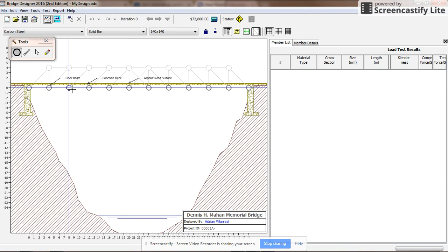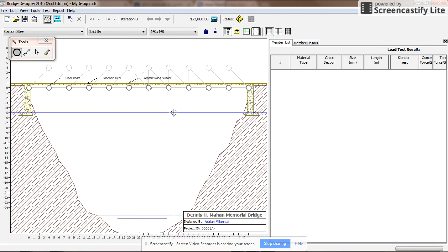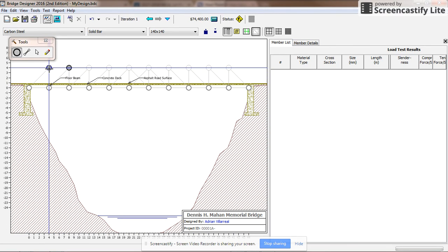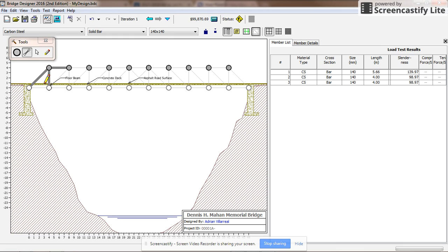So now you get this, guys, and you'll see there's an outline of what your bridge should look like. Wherever you're going to have beams connected, you can add these points here. Okay, these down here should already be taken care of. Okay, so that's how you add the joints. Now to add members or the beams, you have to draw from one joint to another to connect them, like so. Okay, so I'm going to do 3 just to show you how to get that started.